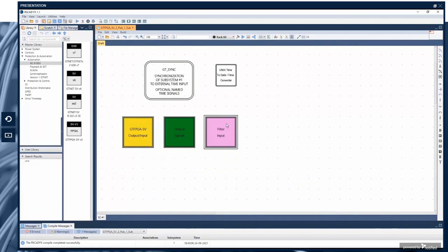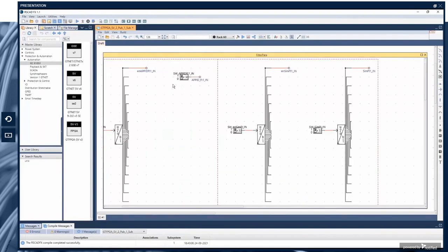The filter input is used to generate those 4 signals used in the port 1 subscription. First one is for application ID enable or disable filter, and the next is the actual application ID filter value used for filtering. Similarly for the simulation flag and the simulation flag value.